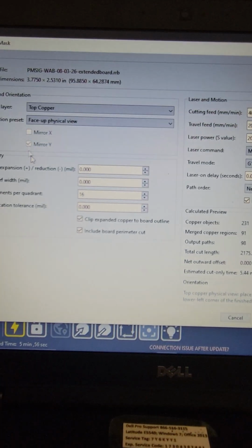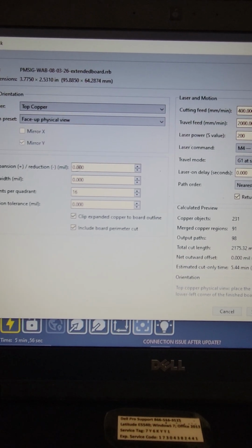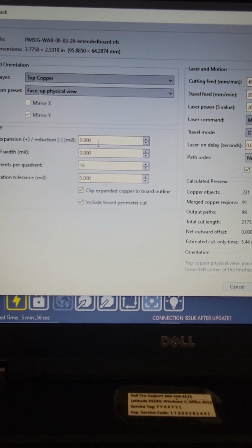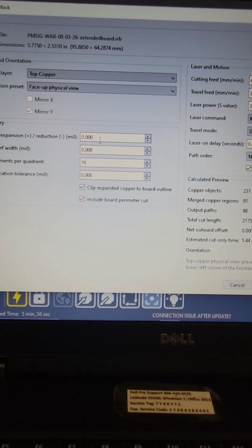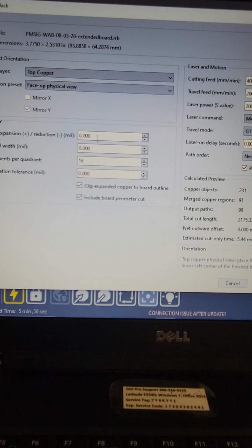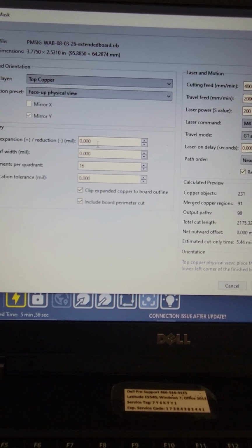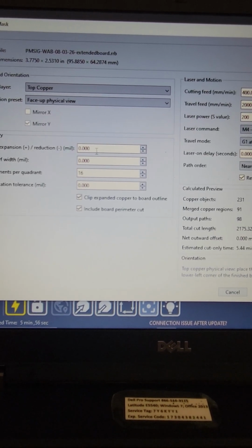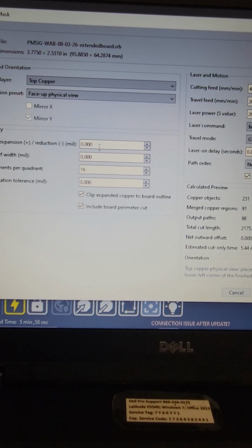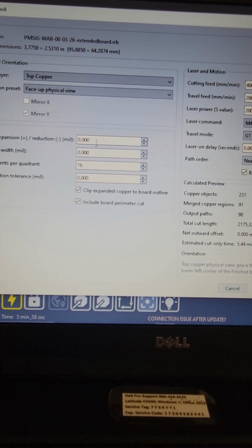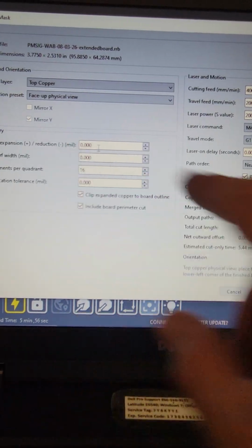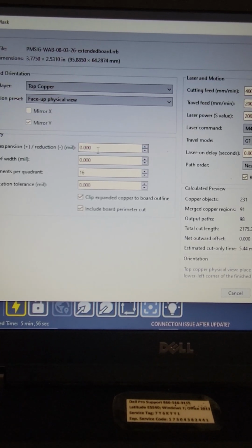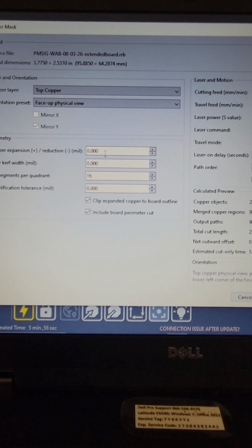This geometry configuration is going to expand or contract from the original artwork, because when the laser cuts the mask that's on the board and you put it into etching solution, the etching solution will tend to undercut the tape a little bit. So you end up with traces and pads that are smaller than they would be in the drawing originally. So this gives you the ability to expand. I put contraction in there, even though you wouldn't probably normally use that, but you can go either way.